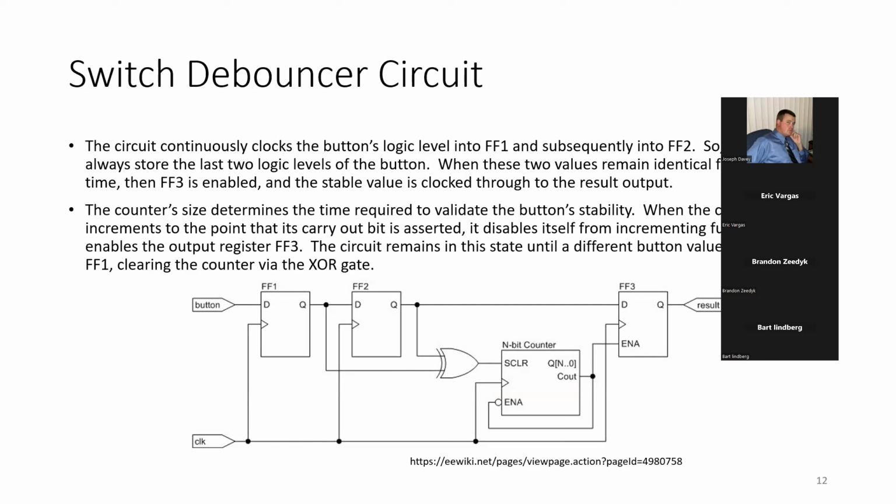In this switch debouncer circuit, I start with this input, and I have here 2 cascaded flip-flops. They are working at the same clock.